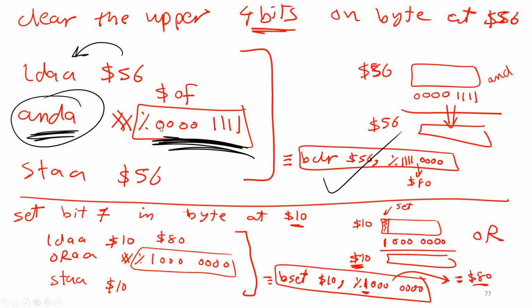Oh, how did you make it? This one is different from this one. Yes, they are different, because here the one is going to mark. You need to identify which bits you want to clear. But here, no. Here this is logic AND, and I know from logic AND that 1 means no change, 0 means clear. Because I want to clear these 4 bits, I'm going to mask these 4, clear them, and put 1 1 1 1 here so there is no change in these 4 bits, and then I'm going to put it back in 56. Okay, guys. One more example. Any questions? One more example.